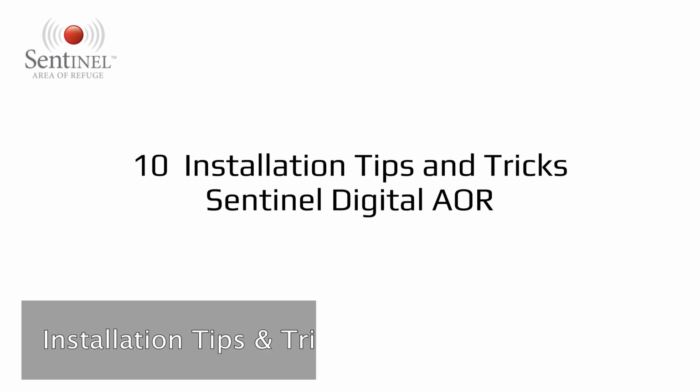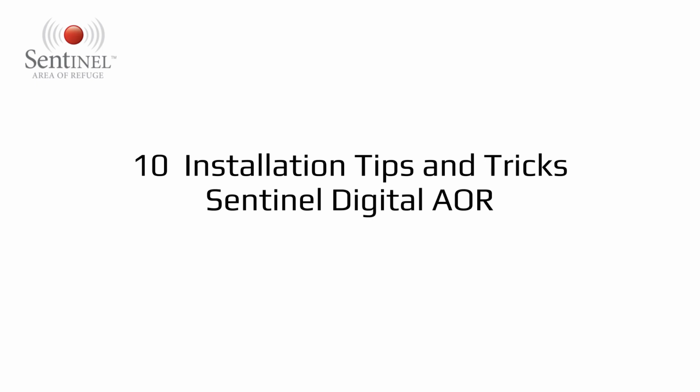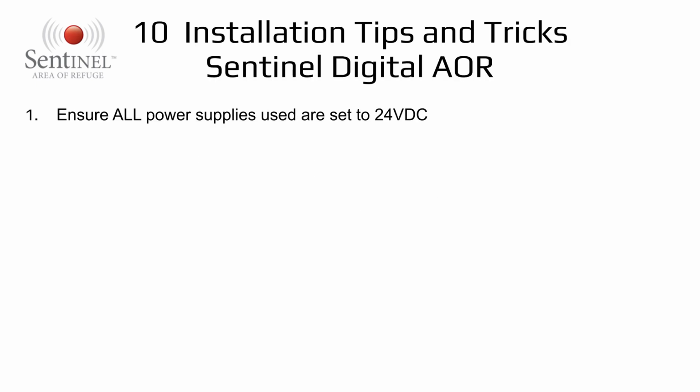Now that you're ready to install your system, we have 10 tips and tricks you can use to make sure your installation is seamless, quick, and correct. Number 1, ensure all of your power supplies being used are set to 24 volts DC. Each power supply comes set typically at 12 volts DC from the factory and may need to be set to 24 volts DC. You never want to change the voltage while the power supply is energized. Always de-energize the power supply, then switch it to 24 volts DC, then re-energize the power supply.